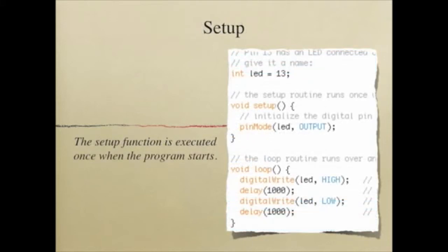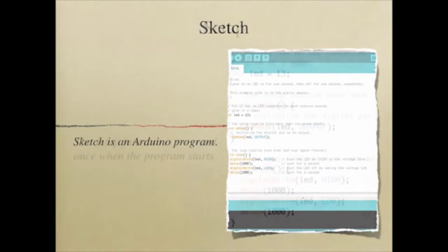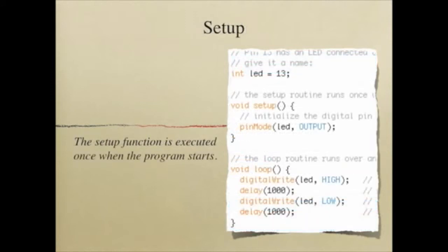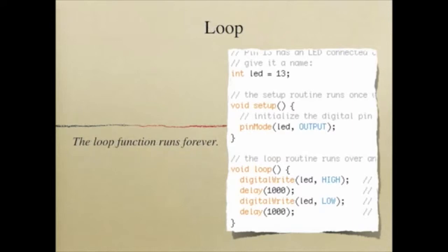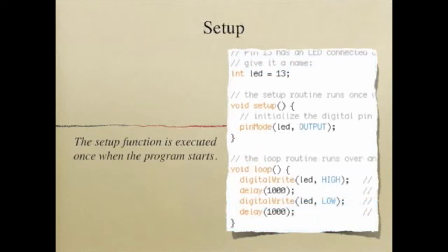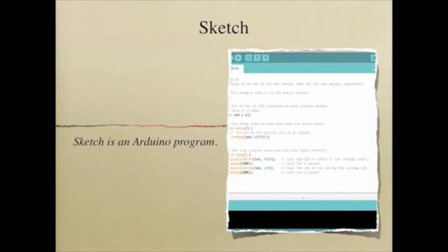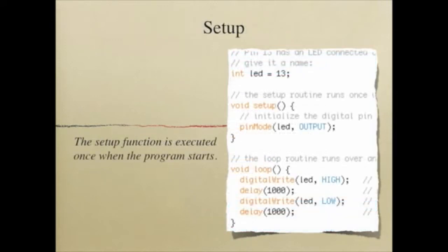In this example, you may also notice several Arduino functions, such as pinMode, digitalWrite, and delay. The pinMode function basically says what direction I want for that pin. When I say direction, it means it can either be input or output, but not both at the same time.